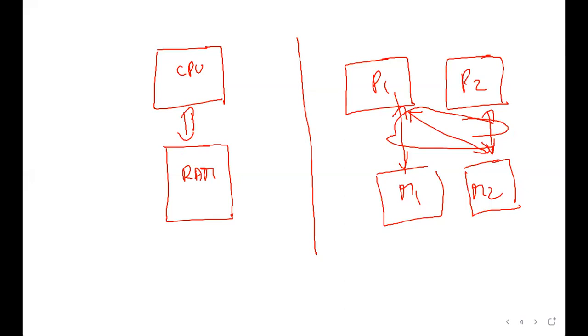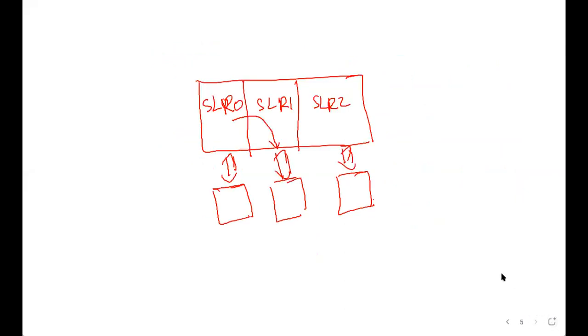In addition to SLRs, the other way you can think about optimizing throughput is through how you design the usage of memory inside the FPGA dies themselves. If you remember, we have distributed RAM, block RAM, and UltraRAM. Exactly how you map and fetch the data that you need, and how you architect the memory inside the FPGA, will make a difference to the speed of computation. Yes, very nice. Actually, that is the next thing that I wanted to discuss.